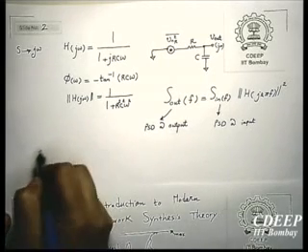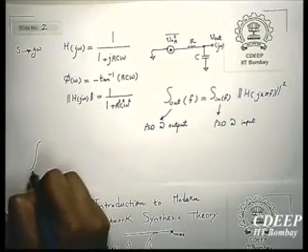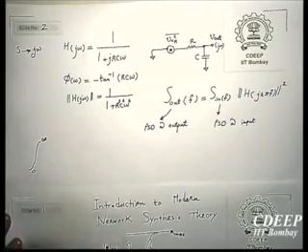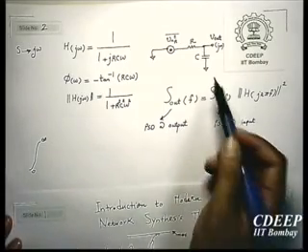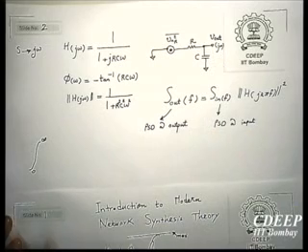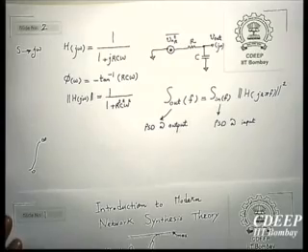Okay, so I consider the whole range of frequency from 0 to infinite, and then see, because as frequency increases, this level reduces, therefore this integral won't be unlimited. But if you have a single resistor, practically, ideally, if you want to derive RMS noise for a complete range of 0 to infinite, it will be infinite value. But here it won't be, okay?